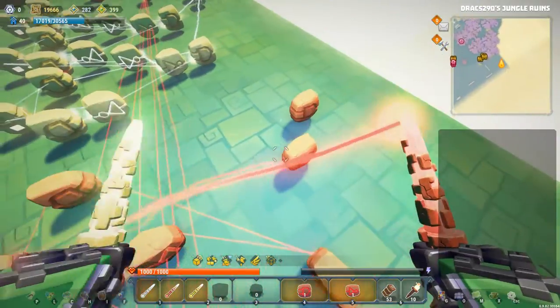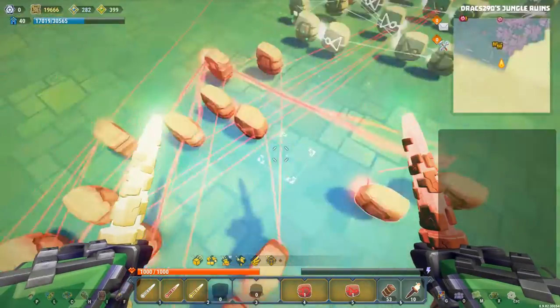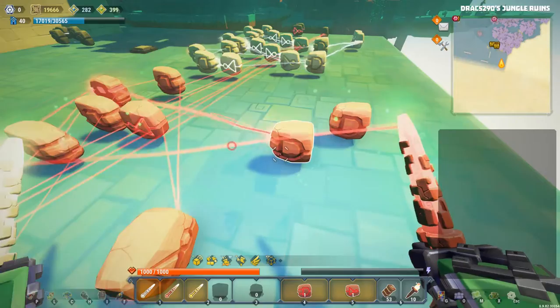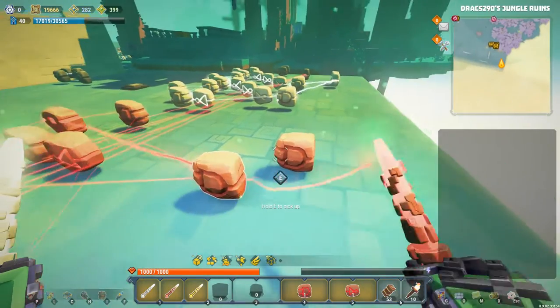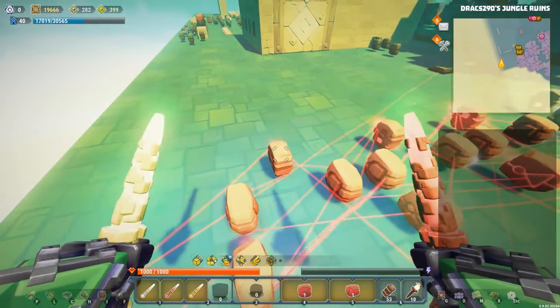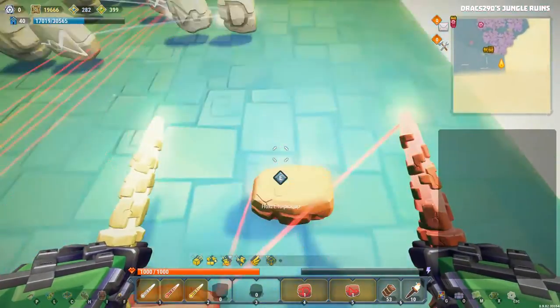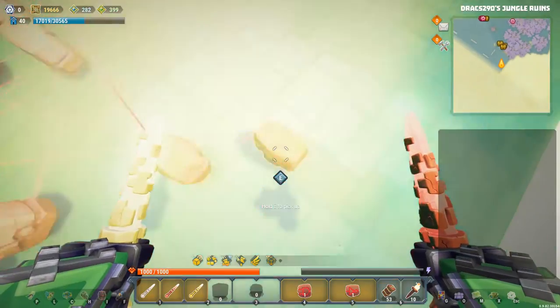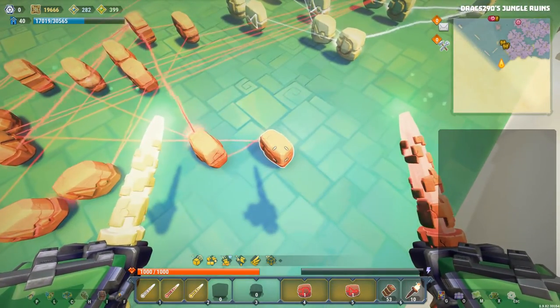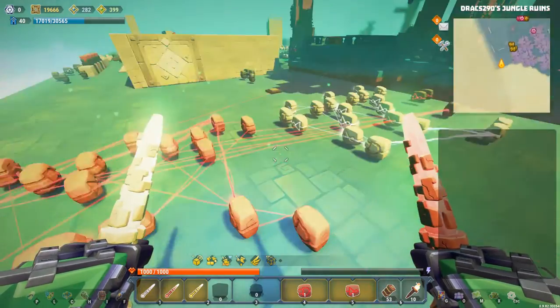So we're going to run one latch into the A side of this guy, and another latch into the B side of this guy. And then we're going to run that into the A side up here, just like that. And then we're going to run the final latch that we haven't run yet all the way down into the B side down here. So now this AND gate here is going to turn on when all 3 of those latches are on at the same time.